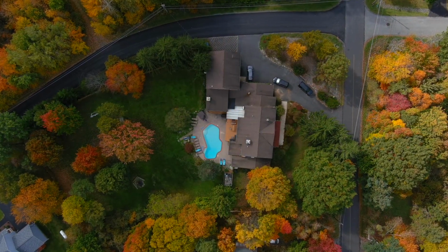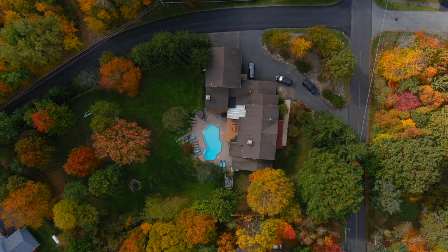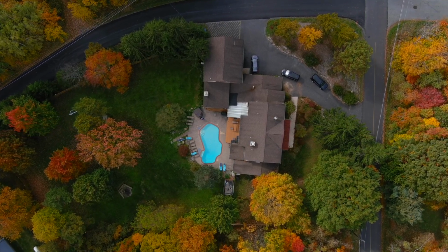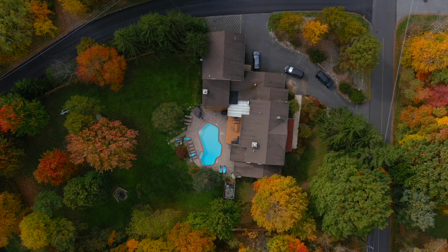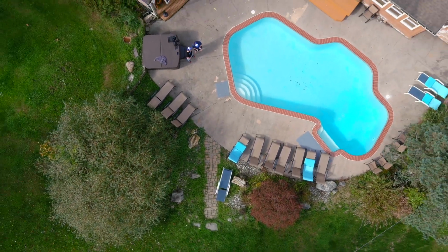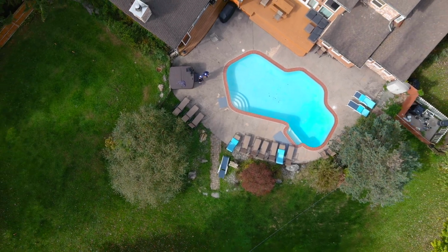If we fly over a building with a camera facing directly down, we will not see those vertical features nearly as well, and your 3D model will have a melting or waterfall type look to it. While taking off, always be sure your drone is clear of any surrounding obstructions, including anything above it.